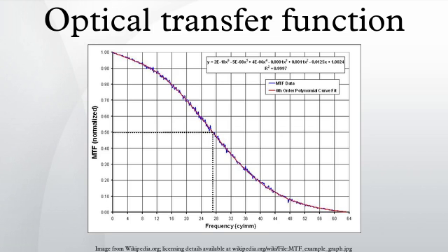In practice, this is far from the case, and spatial frequencies that approach the Nyquist rate will generally be reproduced with decreasing amplitude, so that fine detail, though it can be seen, is greatly reduced in contrast.